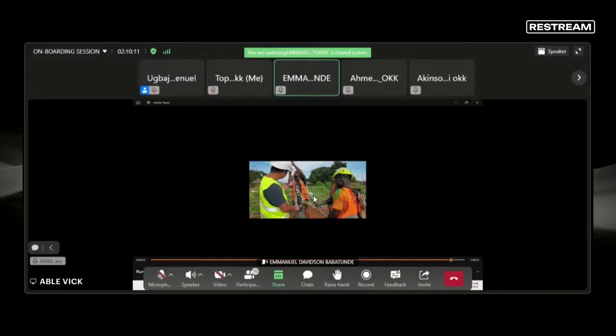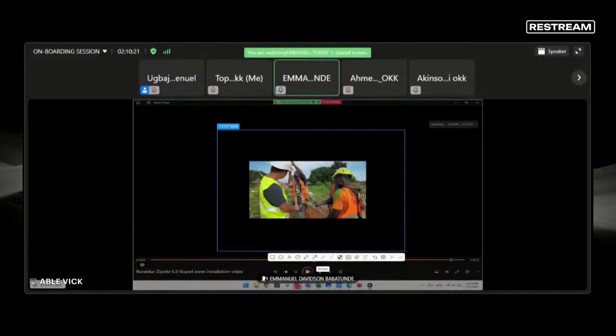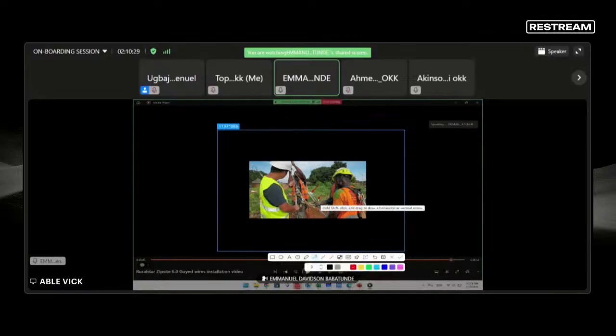Don't pull this thing down. Whatever you are doing, your tension level should be at the tip here, at the tip of the U-bolt, like this. This is the tip I'm referring to. You should drop it there. Don't use your spanner and be adjusting this thing down to go and install here. It's wrong. What we want is for the tension to be achieved at this top.